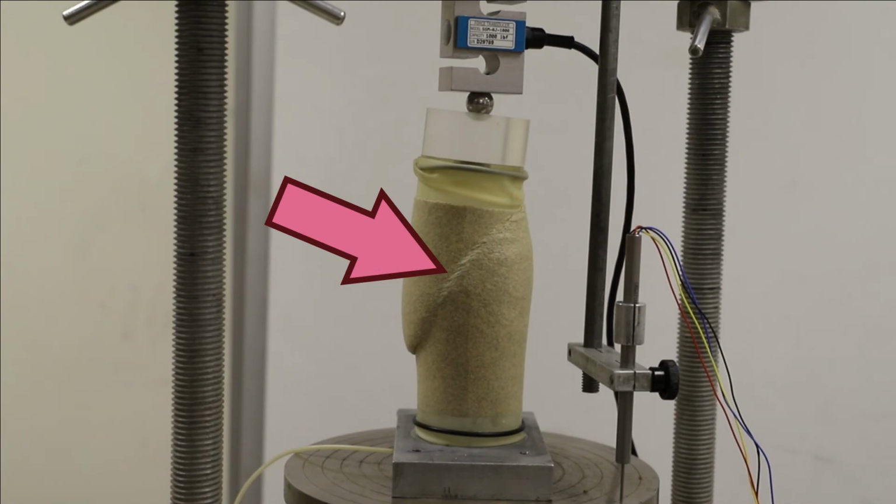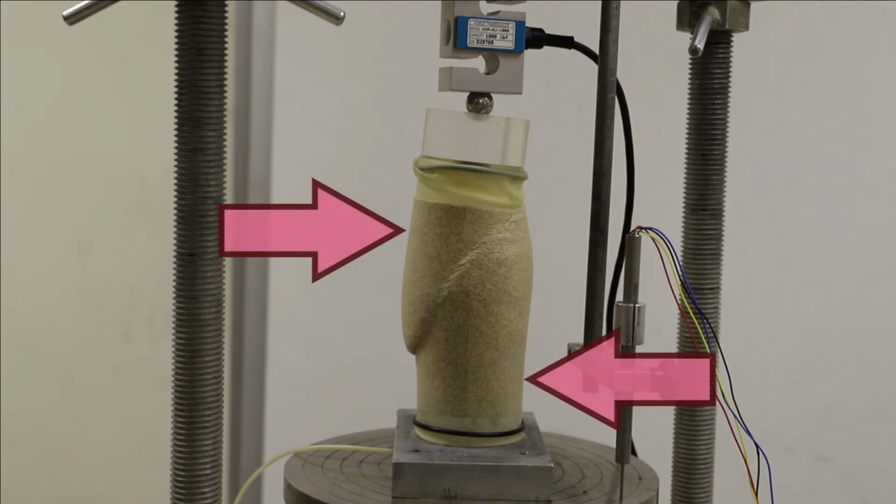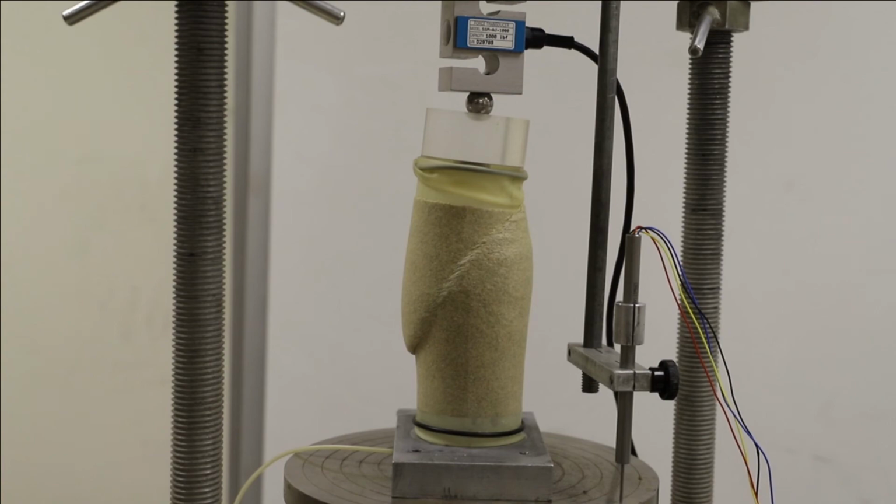localization of the shear. So all the deformation that's happening now isn't happening uniformly across the height of the specimen. It's all happening in this localized diagonal zone, and that's because the soil up here is denser, the soil down here is denser, and the soil within that localized zone dilated when it sheared, and so now it's the loosest plane in the sample.